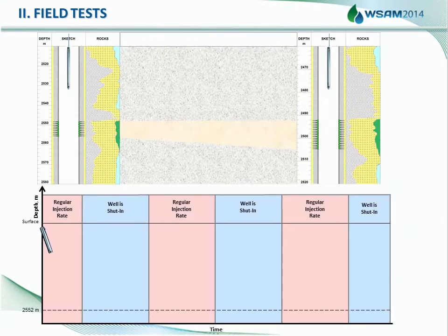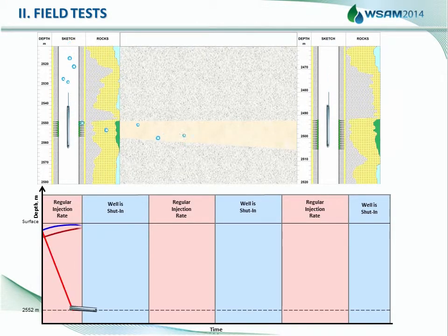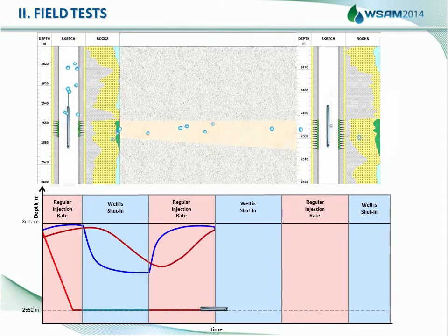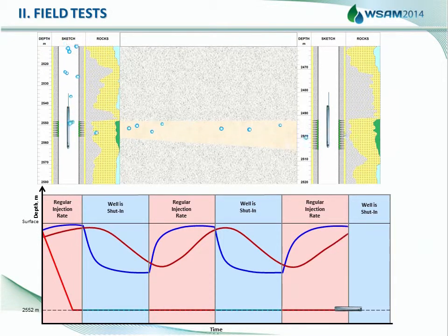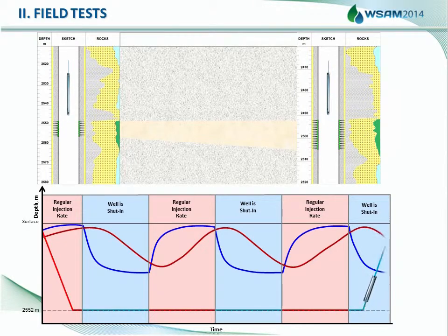The tools are run into the reservoir top. Then, pressure recording starts. The generator well is shut in for a half period and starts to flow for the second half period at a constant rate. This procedure is repeated for the second period to create a perturbation at the receiver well. After the survey, the tools are retrieved.